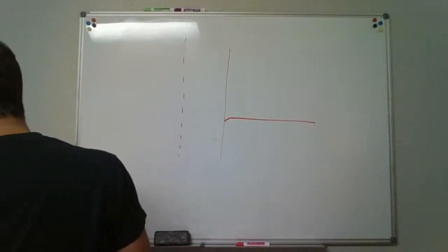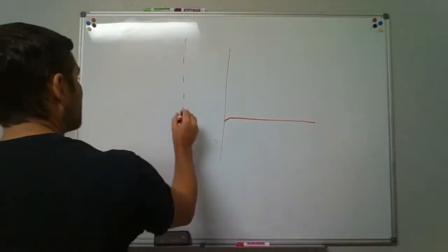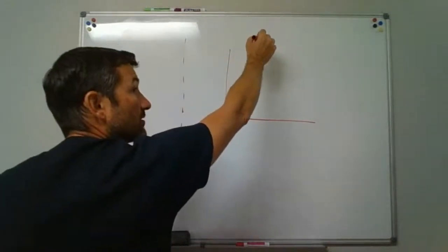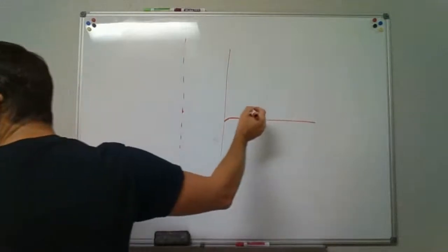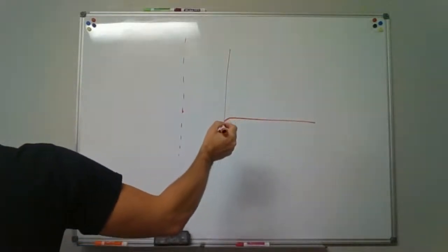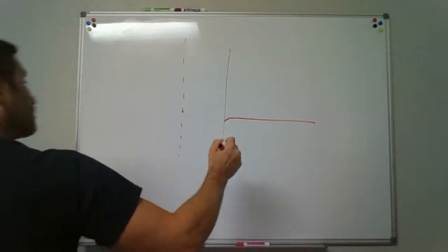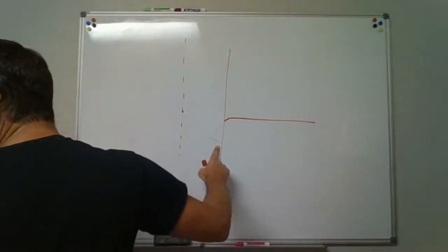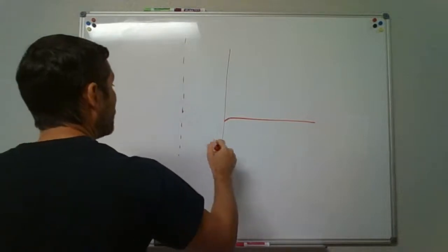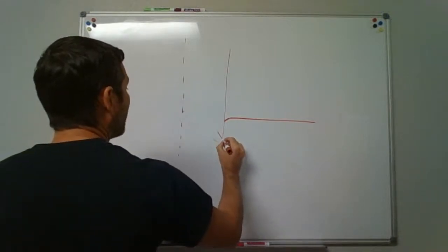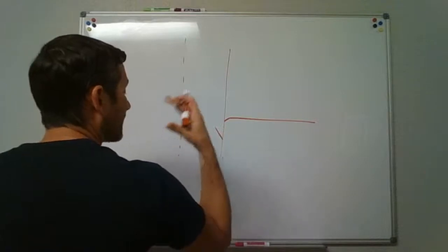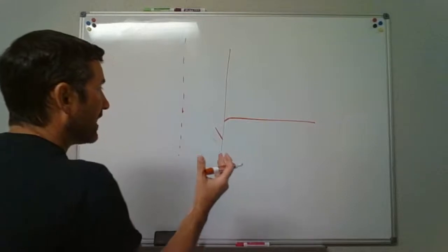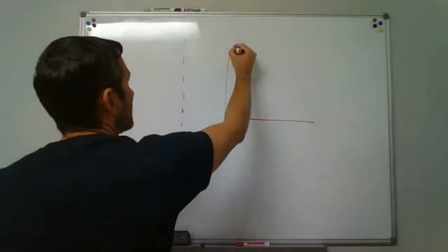So doing it, the size is going to be the same as this size. Right, there's going to be a relief in it. You started with the top floor and counted your way down. And you come to the lower end of the relief vent shall connect to the soil. So talk it through. It's going to connect to the soil or waste stack through a Y fitting. Okay, so as you're reading, try to form the picture in your mind or start to draw this out as you go.